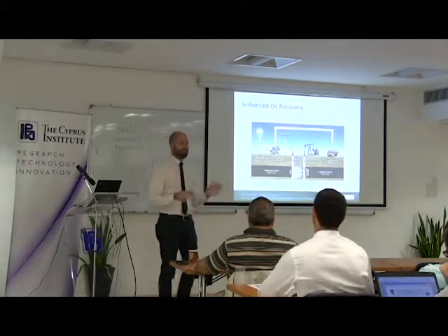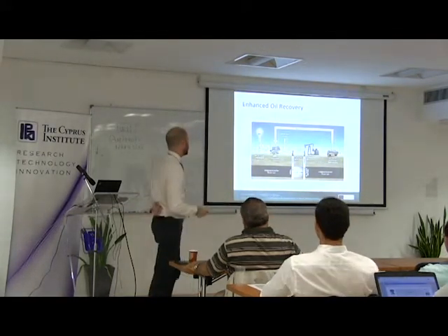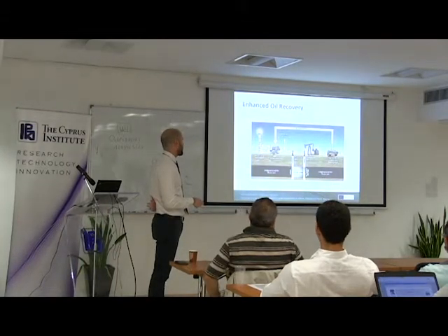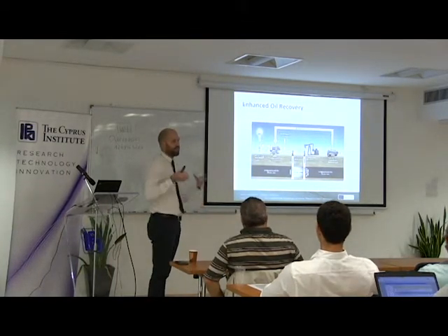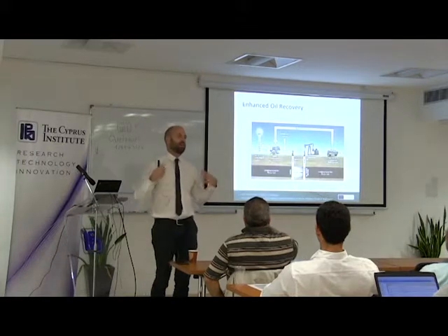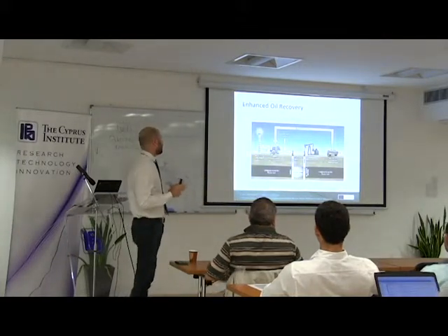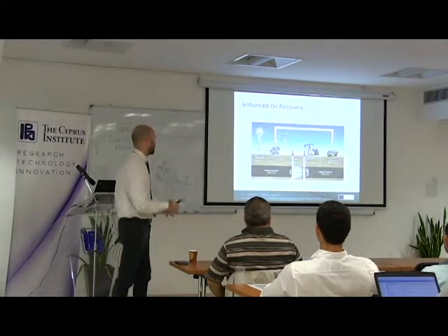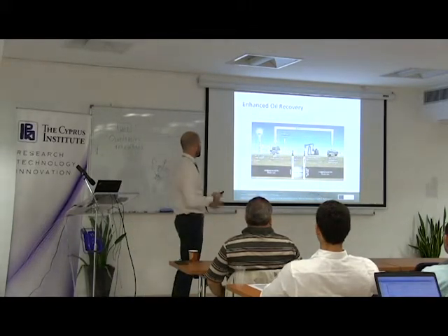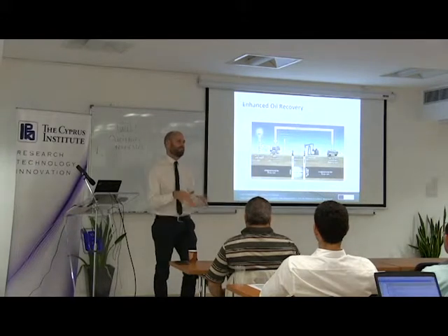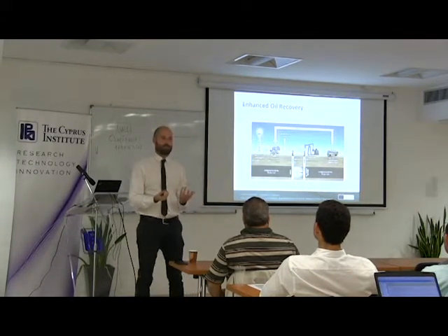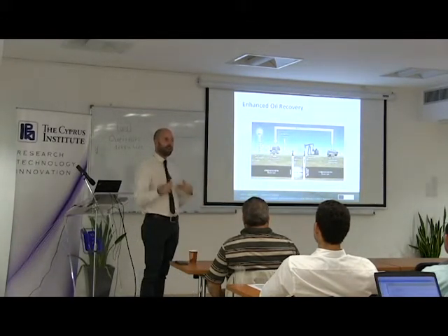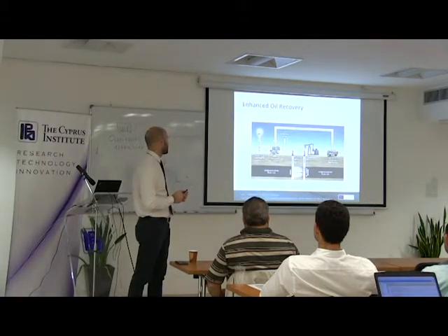You may know, if you're familiar with the oil industry in general, but especially with heavy oils, that reservoirs are porous rocks, and in order to obtain the so-called flow assurance of the hydrocarbons contained in the reservoir, you need specific characteristics of the pressure of the reservoir and of the viscosity of the fluids, in order to ensure a correct outflow out of the wells.